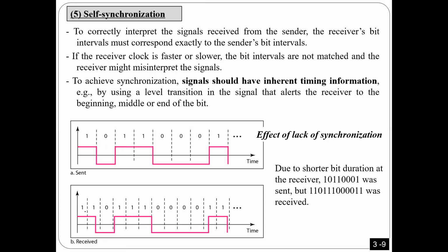because here I'm going to consider this is the time for 1 bit, the time for 1 bit, the time for 1 bit, the time for 1 bit, but actually what you see was different. So for the same signal here, I'm going to receive 1, 1, 0. So look here, you transmitted 1, 0, 1, 1, 0, 0, 0, 1. But what I'm going to receive is different, because we don't have exactly the same duration, or it's maybe shifted. It's not going to start exactly at the same time. So two things, it has to be the same duration, and also it has to be synchronized, meaning at the same time. If it is shifted, you are going to transmit something, I'm going to receive something else. And that's what happened here.